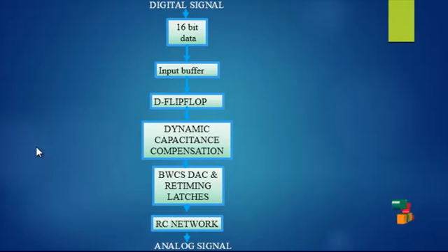A buffer is an amplifier that provides an interface between mismatched circuit elements. It is a unity gain amplifier packaged in an integrated circuit. Its function is to provide sufficient drive capability to pass signals or data bits along to a succeeding stage. Voltage buffers increase available current for low impedance inputs while retaining the voltage level. Current buffers do just the opposite, keeping the current the same while driving high impedance inputs of higher voltage levels. Next, the output of the buffer is fed into the flip-flop.